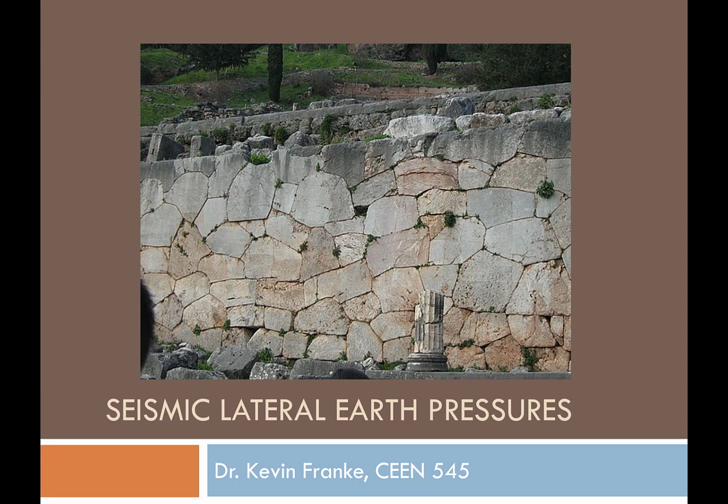It's a gravity retaining wall where the weight of those stones is what is holding back the soil and the rock behind it. But notice how intricately cut those stones are and how well they fit together, which I think is one of the interesting keys why that wall is still standing. It was never really engineered, at least not engineered to the extent that we would engineer such a wall today. But I still find it marvelous that such a retaining wall, such an historic retaining wall, is still standing. And there's many walls similar to that located around the world.